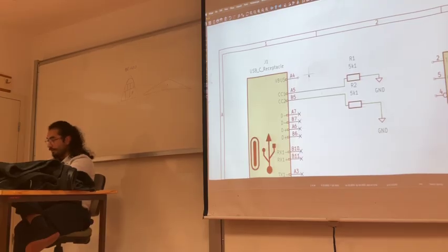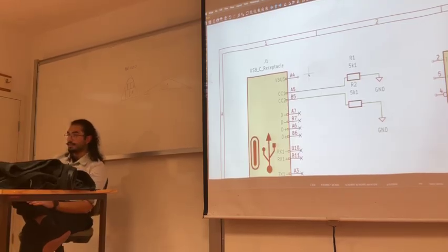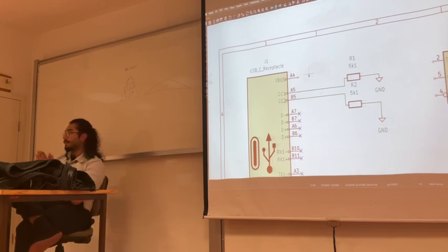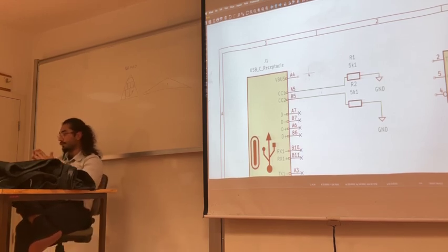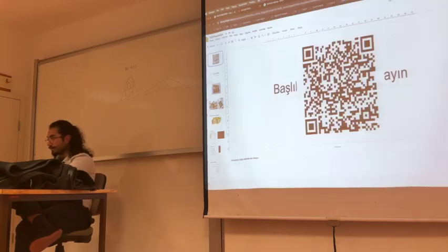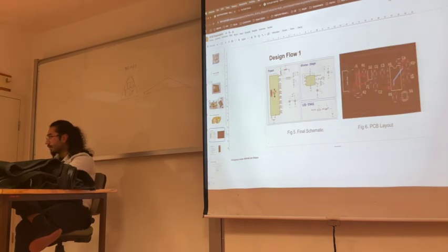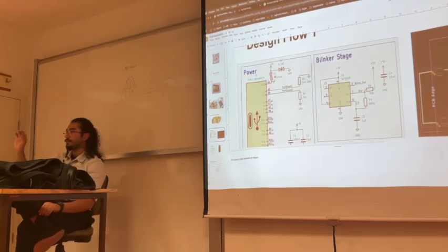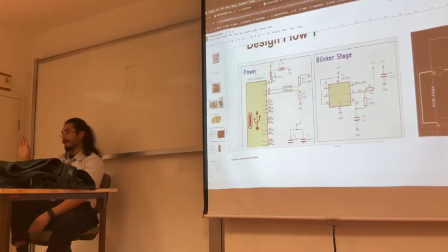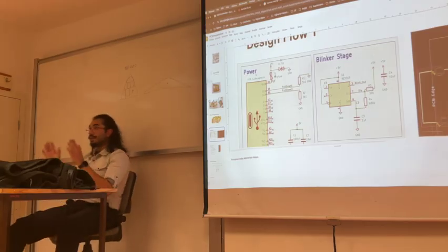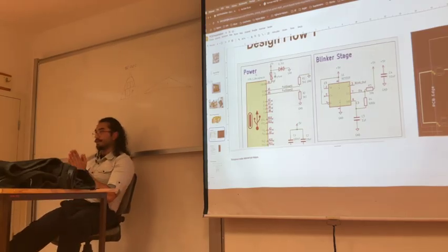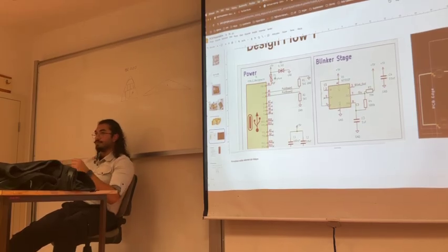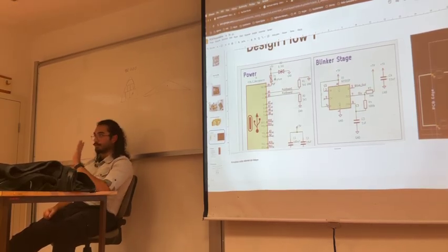Okay, I'm going to add two more components. One is a fuse, and the other is a TVS diode. What they are, I'm going to explain them first, and then I can show them later in the schematic. So, I'm going to add a polyfuse, which is a fuse. I'll just explain what a fuse is first. If you get a large current that is larger than the polyfuse rating, larger than a fuse's rating, the fuse just shuts itself. Sigorta in Turkish.